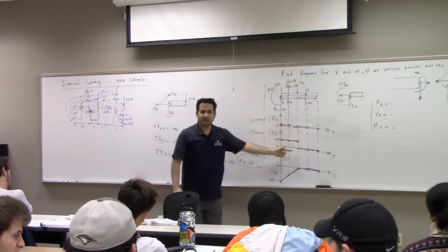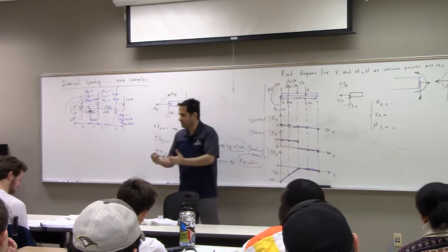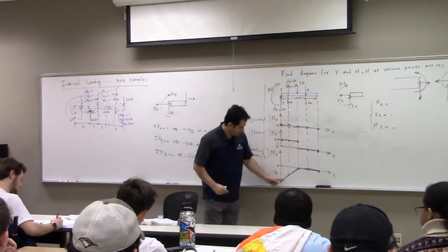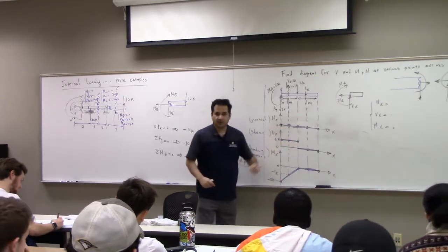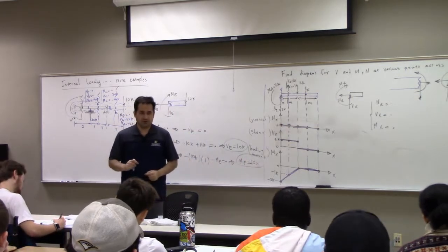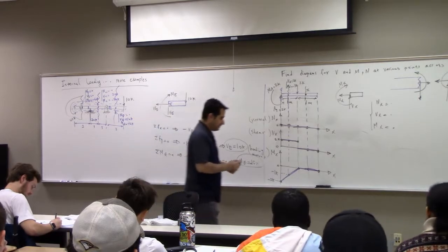This kind of modeling, either manually finding the shear moment diagram or using software to obtain it, your job as an engineer is to look at the critical points here: jump in the shear, maximum bending. Those are the points that you design for and consider in your analysis, right? Another example.